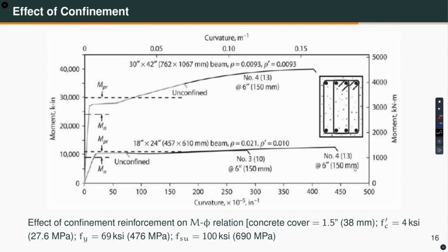Recall from lecture number 21, where we talked about the stress strain response of reinforced concrete, how it improves due to confinement. So, if you use more and more confining reinforcement, what do you see? You have improvement in the curvature ductility. That is number one. Number two is, notice what is going on here. Some interesting thing is going on. So, if you have an unconfined concrete, it fails here. The concrete reaches crushing strength, right?